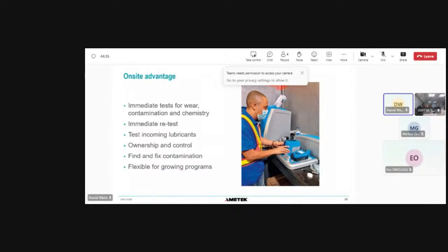So in the previous example I shared with you, they were able to show that within just 6 months of starting to do this with a fleet of engines, between the reduction in unnecessary oil changes based on OEM alone, combined with sampling just at the right time, they saved about $300,000 all told, just in the first 6 months on those 13 engines and applications.